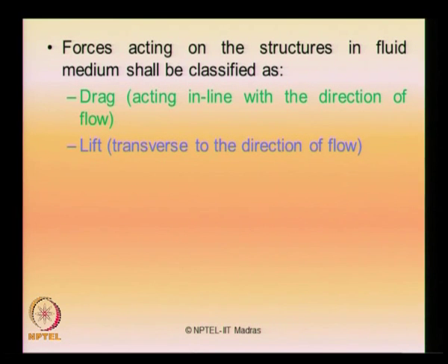So, the forces acting on a structure in a fluid medium can be classified into two parts, as we all understand. One is drag, which acts in line with the direction of flow; the other is lift, which is transverse to the direction of flow. There are two kinds of forces which generally act predominantly when a member is placed in a fluid flow. One is a drag component which acts in line with the fluid flow. The second is the lift which acts in the transverse direction to the direction of flow.